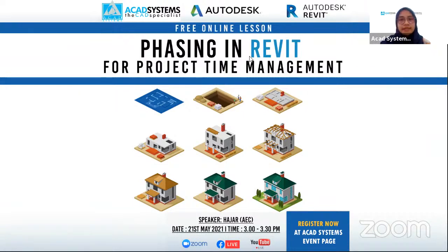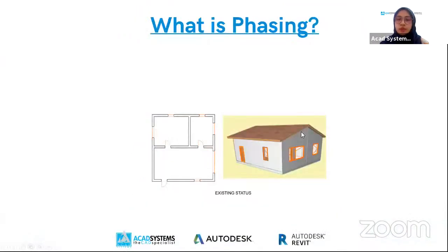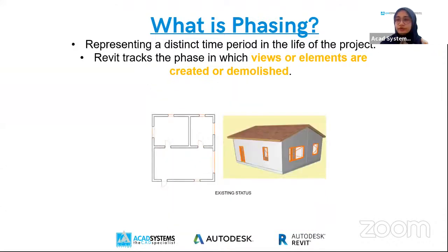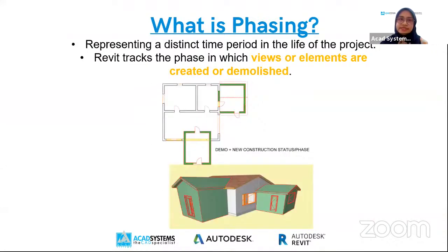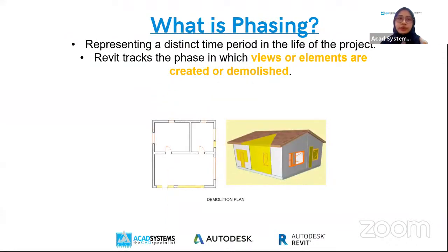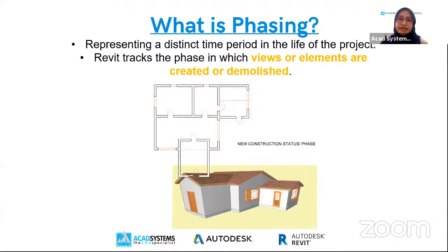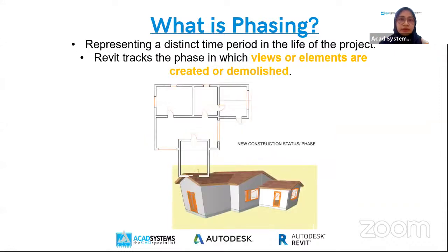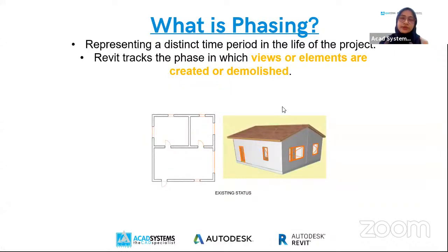So what is phasing in Revit? For a renovation project, we need to represent the existing and the demolished features within the model when we model. Phasing is very useful inside Revit because you can represent a distinct time period in the life of the project. We can use this phasing tool to track the phases, the elements that we have created, or the elements that we have demolished.